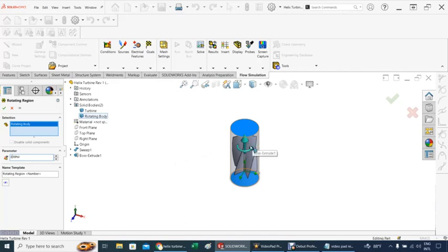Free spinning, you are not adding torque, you are not extracting torque, and the blade will get to whatever maximum RPM possible, and you can find that value by doing an optimization, or you can do several runs at different RPM to find out where is that RPM in which you have zero torque.